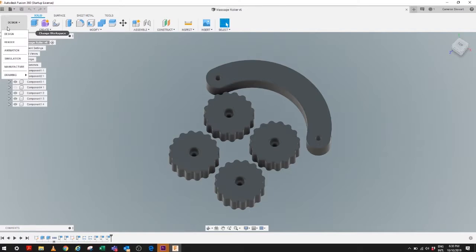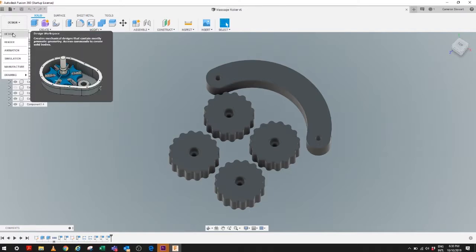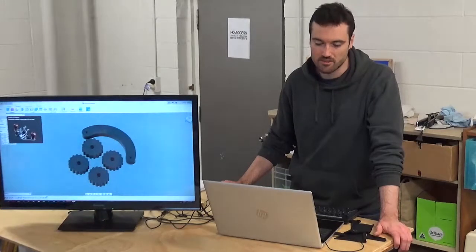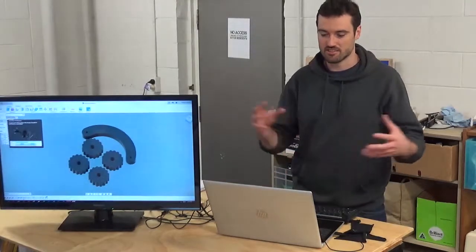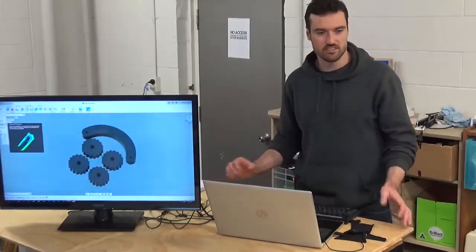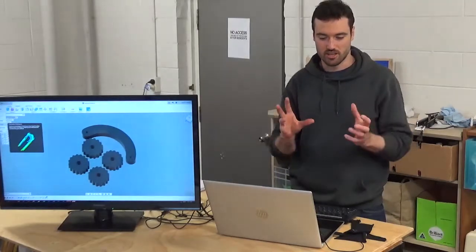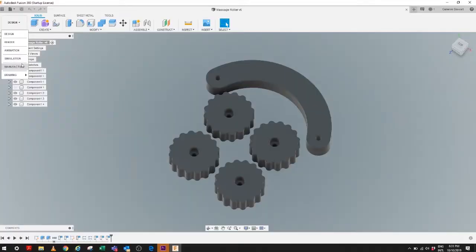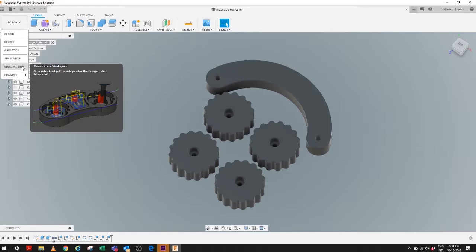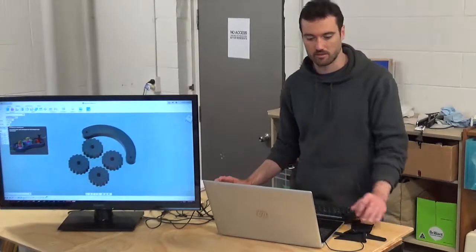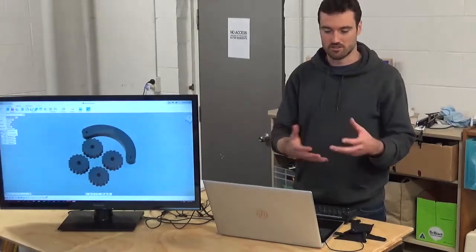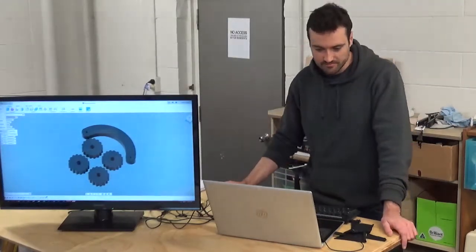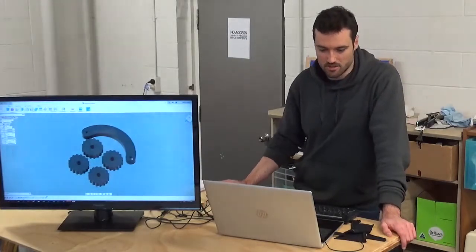So basically in Fusion 360 you have these tabs down the side so you can design your parts, render them so you can create photorealistic renders, animation, so exploded views, how stuff goes together, simulation, so you can do forces and work out whether the parts are strong enough. Then manufacturing. Manufacturing is where you generate all the tool paths for CNC. So that's the bit we're going to do mainly. And then drawing. Drawing is where you take the parts, you lay them out, and you put them on a traditional sort of 2D drawing. So in this case, we're going to switch straight over to manufacture.